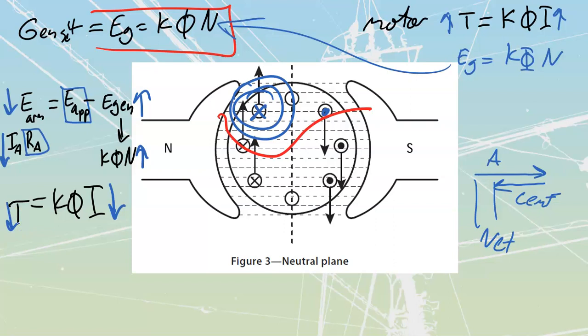So motors are just this wonderfully built thing where all these laws of science work together to cause this thing to respond to changes in load. They will try their hardest. They will work until they burn out, because as we just continue to increase load, we go through this path just in the opposite direction, and we're always going to keep going until eventually we get to that locked rotor, to that stalled motor, which is never going to be a good thing for our motor.